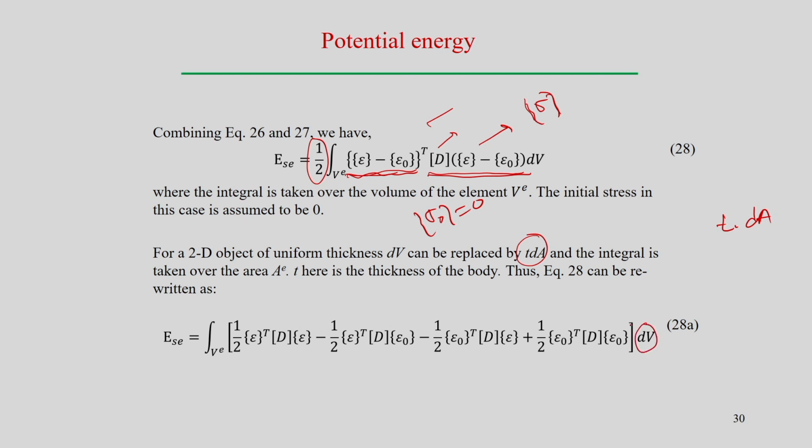We have kept dV also in this case. So, 1, 2, 3 and 4 components are there, and we will get 1, 2, 3, 4 components if you multiply this out. When we write this in matrix form, the compatibility of the matrix can be maintained by keeping a transpose at the particular position, depending on the position of the stress or the strain.